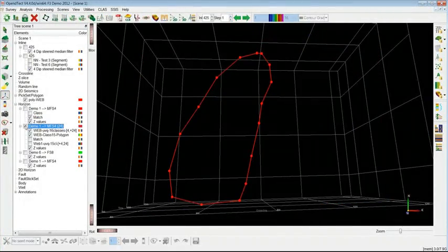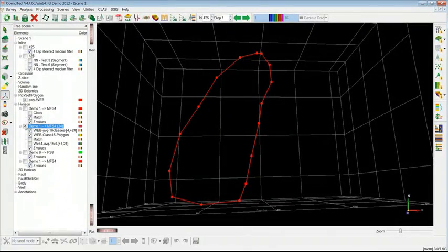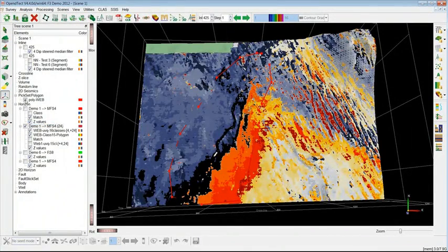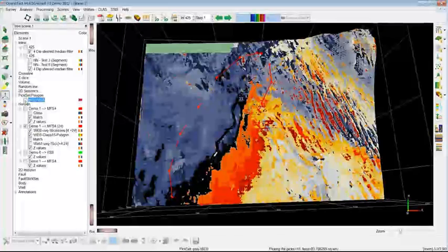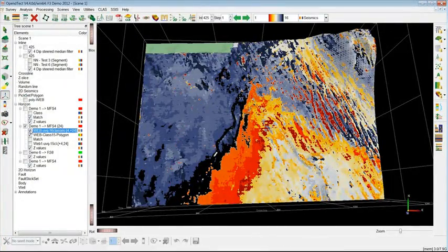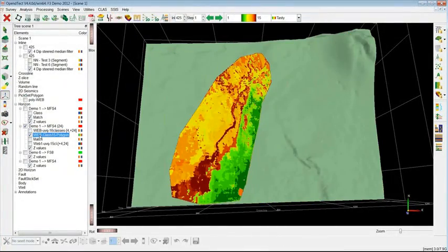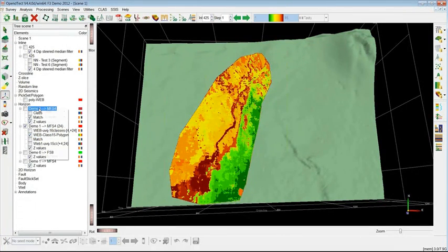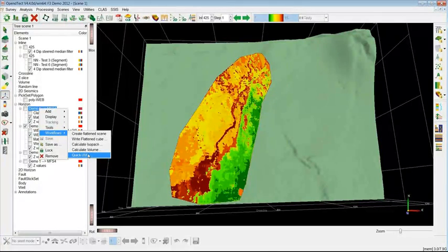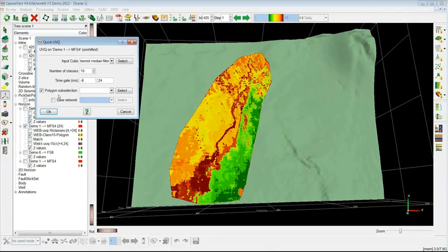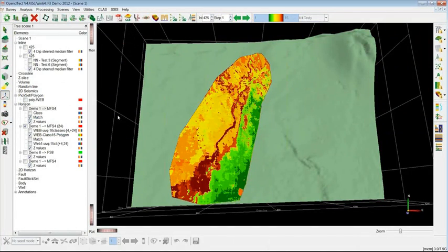I just used some polygon here, and let me show how the result really looks. I'm not going to do that, but when you click, for instance, workflow, quick UVQ, here you have polygon selection. So you can select, just to constrain your cluster to a specific area. So this is how it looks.